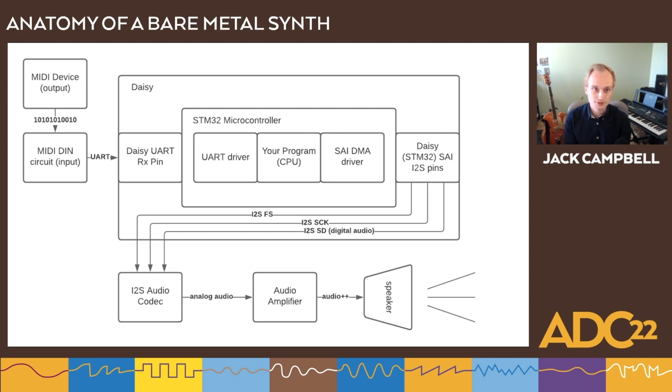This is what our synthesizer is going to look like. It's just a flow diagram, not a schematic, but you'll see we've got MIDI going in there. The MIDI will come in, it is UART in this case, and it'll be picked up on that RX pin, sent into our program, sent out. Digital audio data will be generated in response.